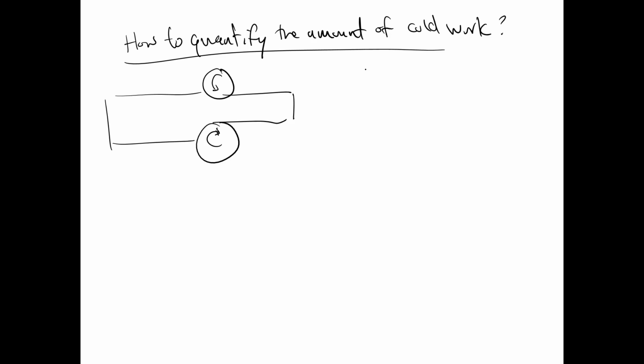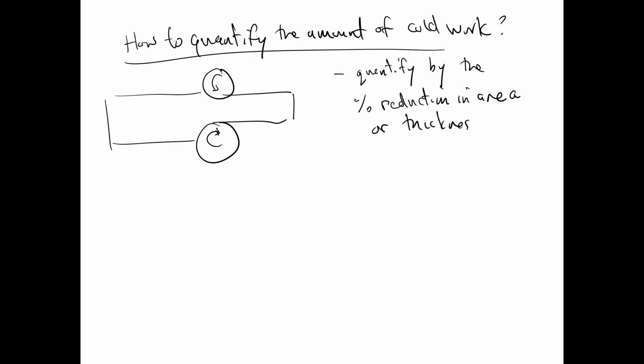So we can often quantify this by literally the amount that you squish this thing. So we can quantify by the percent reduction in area or thickness.